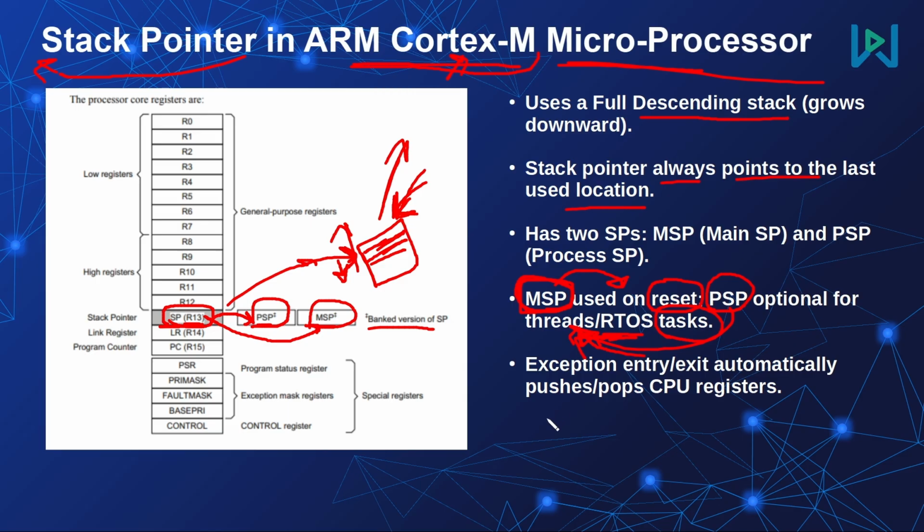The stack area will be used as well to back up and restore the different CPU registers during the exception and interrupt entry and exit routines.